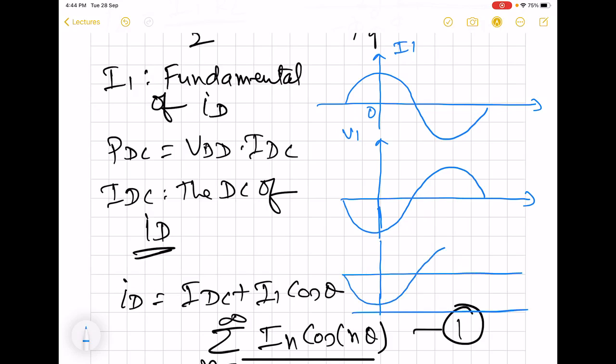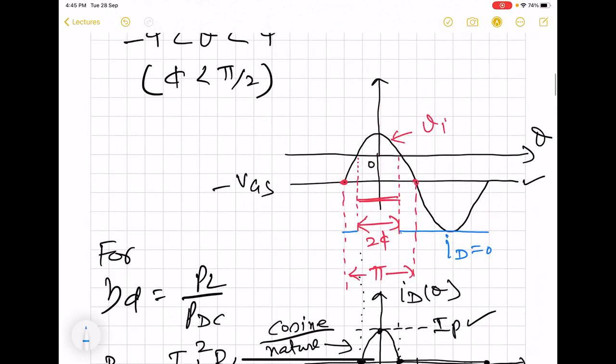In general, it is going to be like this. So this is the total drain voltage. And this is equal to VDD. And this amplitude is what we are calling V1. So here we can see that V1 can be made equal to VDD. There is still room for the growth, this is small amount. And this growth can be made equal to VDD by increasing the input.